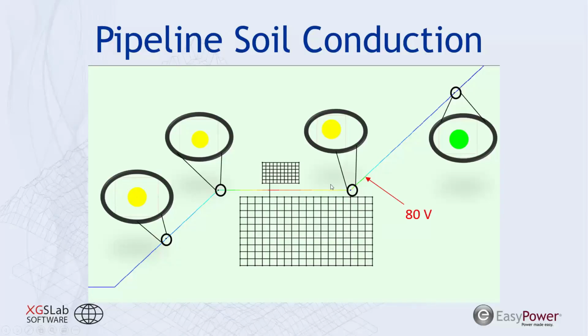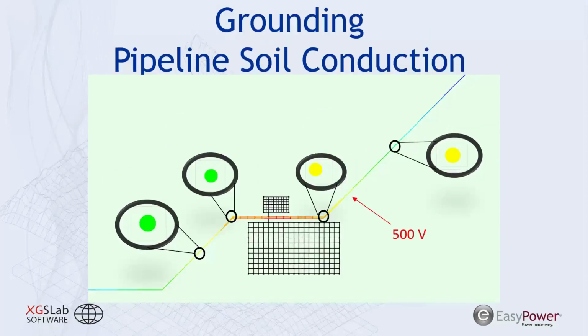Now I want to go through a couple strategies here. And our first strategy is going to not be effective. So one approach for mitigating transfer voltage is grounding the recipient. And when you're grounding the recipient, you have to be cognizant of your location and that location's ground potential rise, or the potential of the soil in that location.